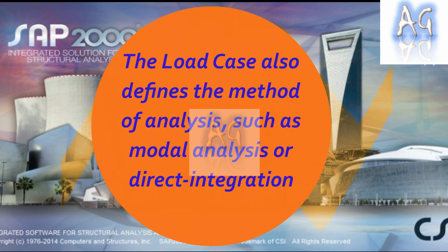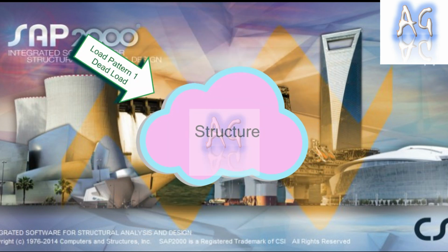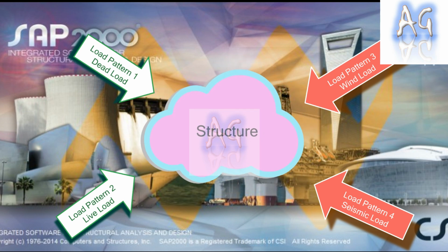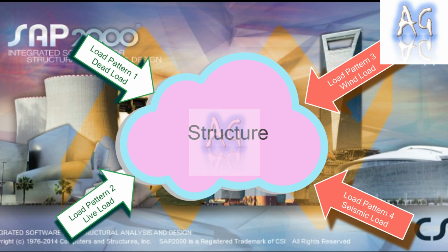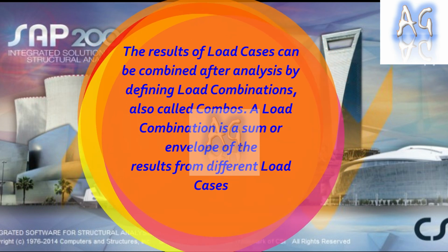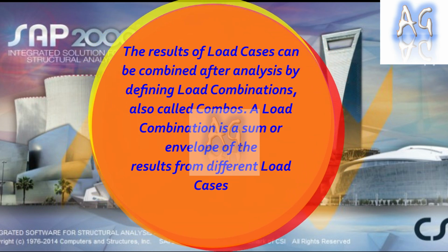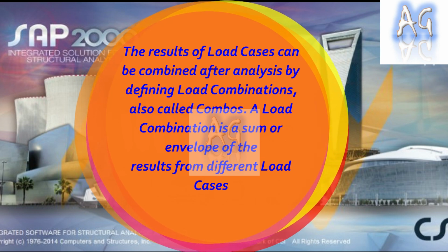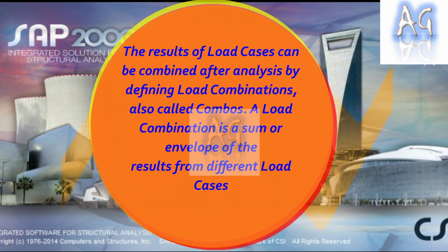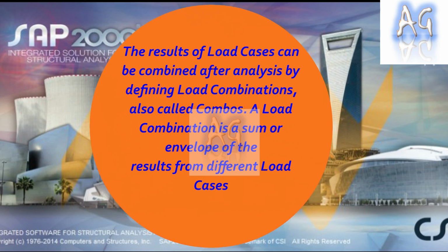A load case may apply a single load pattern or a combination of load patterns. The results of load cases can be combined after analysis by defining load combinations, also called combos. A load combination is a sum or envelope of the results from different load cases.